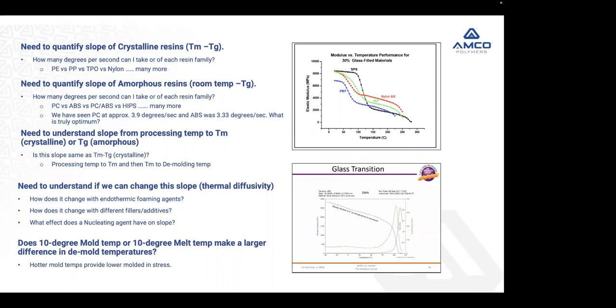So my goal is, I would like to know approximately exactly what I can do and say the best I can do for polycarbonate, and I'm making up this number, say 4 degrees. I can walk up to your press and polycarbonate and say, add 2 seconds to my cooling time. 2 seconds should add 8 degrees to my ejection temperature. So it should come out 8 degrees colder.